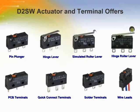This switch family is available in 4 different actuators, including pin plunger, hinge lever, simulated roller lever, and hinge roller lever. It also offers selections such as solder, quick connect terminals, PCB terminals, and molded lead wires or even pitched PCB terminals.